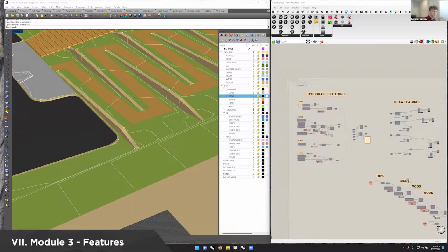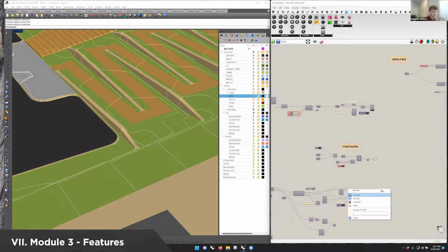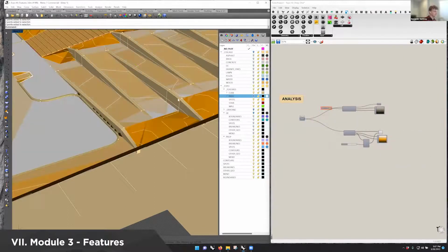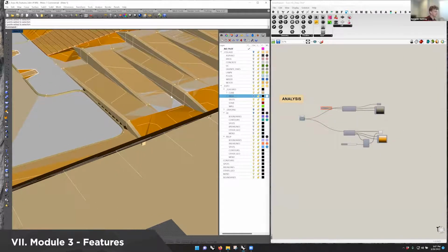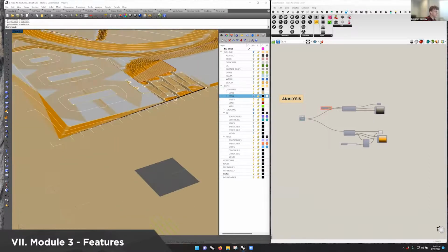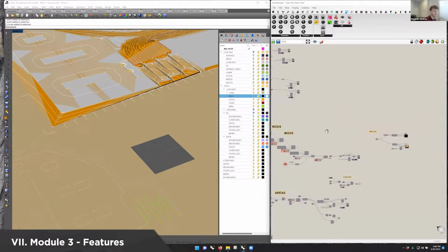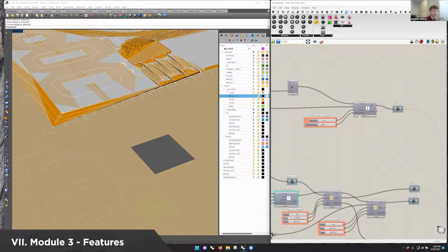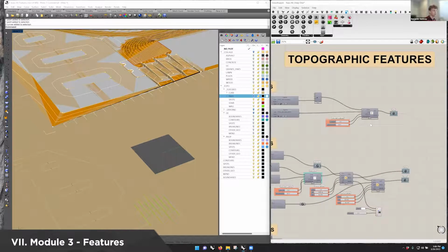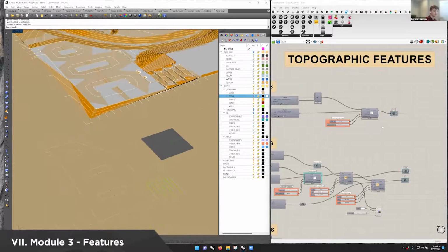And I'll switch from the areas to the slope analysis real quick, just so you can see that a little bit clearer. You can see that the topo is being modified using these spots elevated in three-dimensional space as they relate to their 2D line work down here. These walls don't have to be parallel. They can be different widths at different locations, or they can be 10 feet wide or half a foot wide. You can choose that, and Chris will show you ways using these tolerances in order to control how these get processed together.